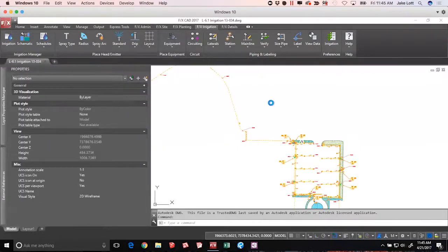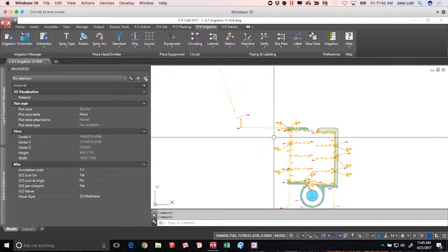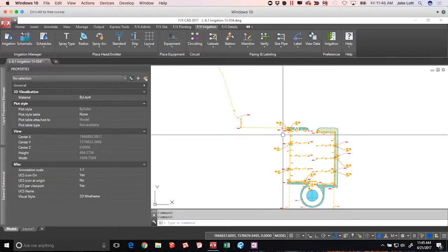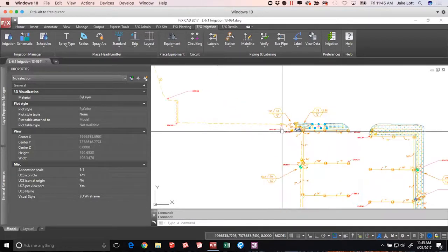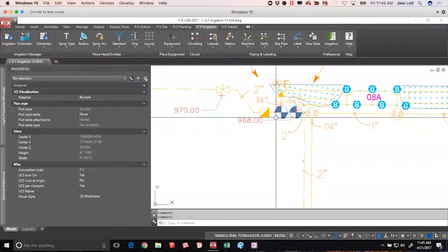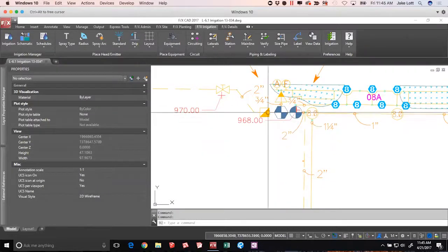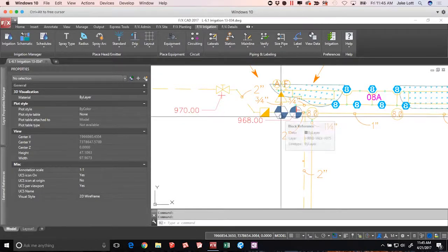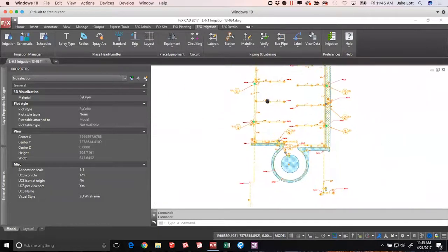One big thing that we stress, as you're drawing, as you're using some of these tools, is the proper workflow. For example, being able to use AutoCAD commands in conjunction with Land Effects items, you got to be a little bit careful. The reason being is that depending on how you use those tools, like our copy features, if you've done them somewhat out of sequence, you are pulling improper data. And what I mean by that is this here.